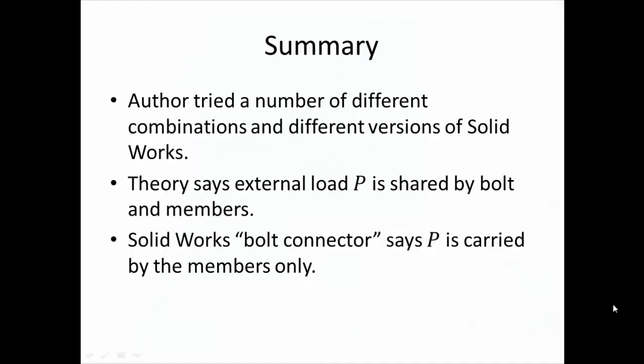The author tried a number of different combinations, for example, tight fit, different meshes, all kinds of different stuff, and even different versions of SolidWorks up to 2015. And the author was not able to get the theory of how the external load P is shared by the bolt and the members to agree with what SolidWorks provides. SolidWorks seems to say that the external load P is carried by the members only.